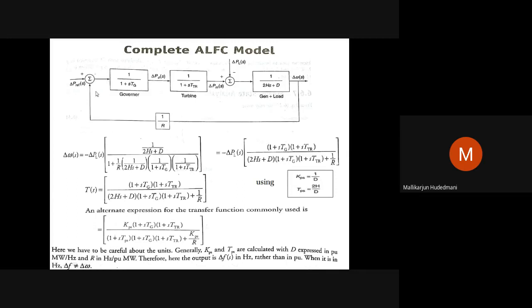By the error setting here, whatever the error we have here, we have to transform delta omega by R as power displacement and set point, actual value and the set requirement. Error has to be input to the governor, and the governor will take care of shifting it, either open the valve or close the valve. Suppose there is a drop in frequency. Let's say frequency 50 hertz has come to 49. So there is a 0.1 drop here. Let's imagine frequency has reduced here. Delta omega is say 0.1. This is to be made 0.